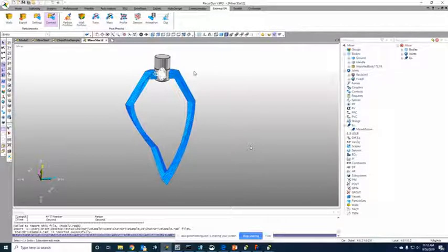I definitely think that this mesh needs to be worked on a little bit. There were a lot of features on the geometry that I imported that really needed to be defeatured before meshing, but for simplicity's sake and for the sake of this example, this mesh seemed like it would work fine, and it does run fine. I do think it needs a bit of work if you're actually looking for results from this, but it'll work for this example.